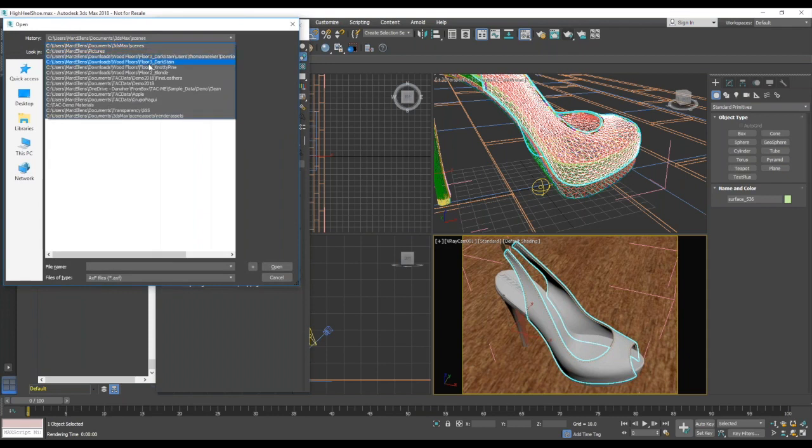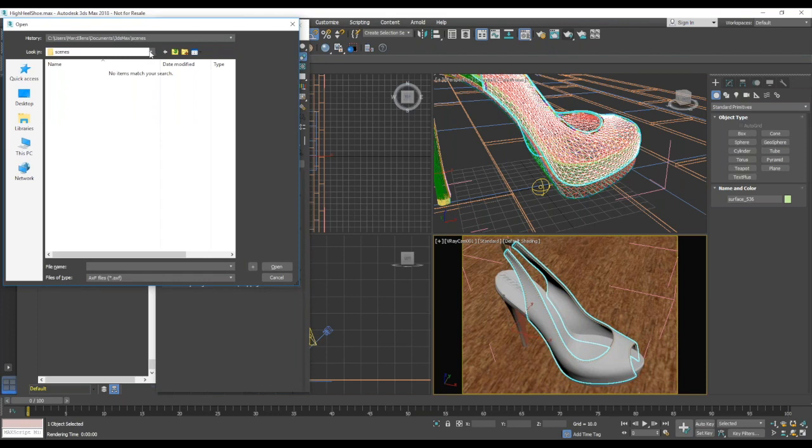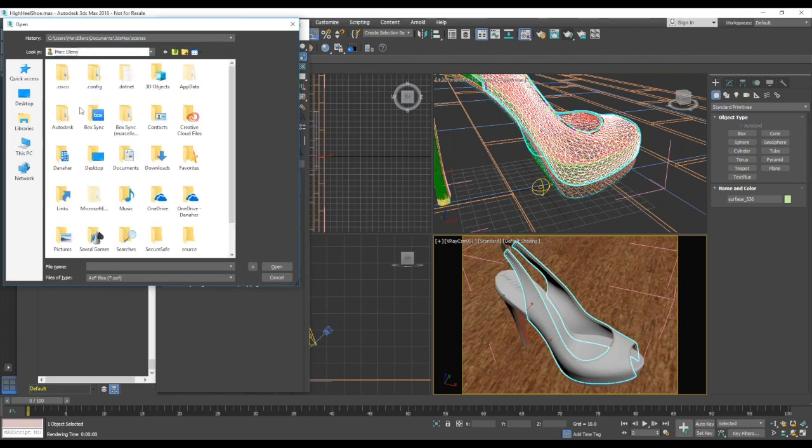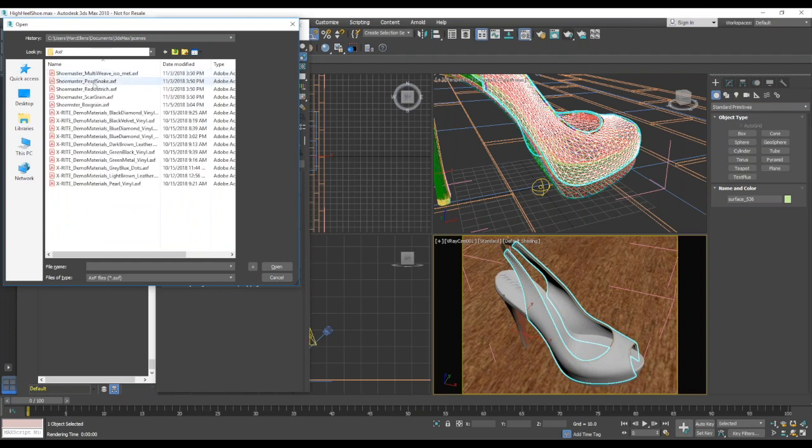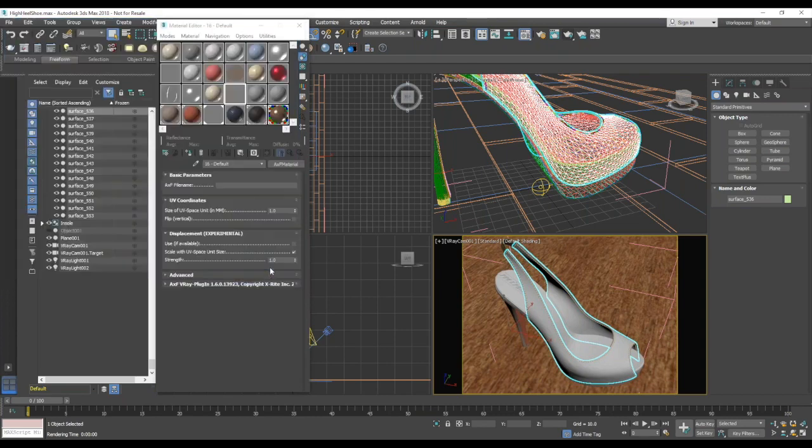And in particular, I want to go here to AxF. And now I have these individual materials here that I can just say AxF. I know that my UV spacing on here is about 80 per, so I'm pretty sure that that's the right sizing. And now, because I have this selected, I can apply that to my selected material and do a test render.